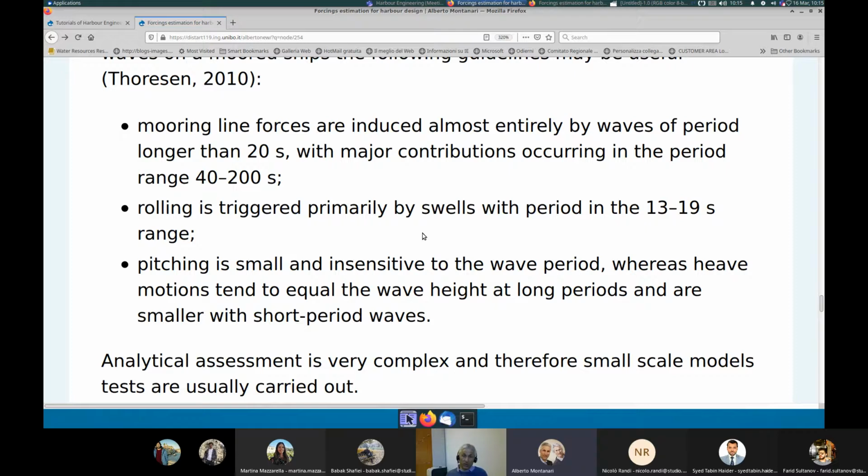First, because you need an infrastructure, you need a huge lab. And second, because the results from a small-scale hydraulic model cannot be merely transferred, cannot be just assumed as equivalent to the real situation, to the prototype. We call the real situation the prototype. So the results that you get in the small-scale model cannot be simply transferred to the prototype.